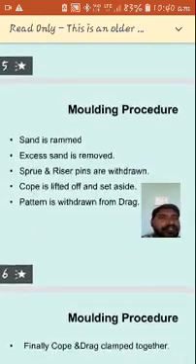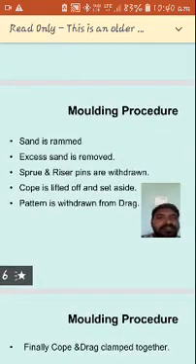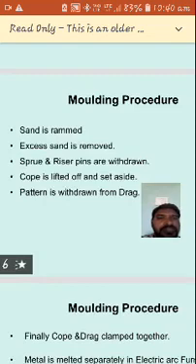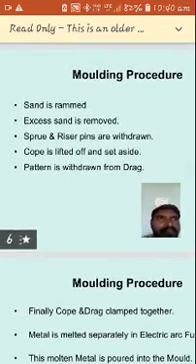Then after completing this operation, the sprue pin and the risers that are placed in position are withdrawn slowly. Then the cope is lifted off. Slowly the cope is lifted up and set aside. You can keep it aside.